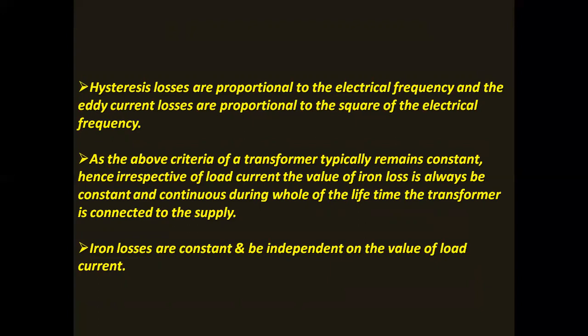As the above criteria of a transformer typically remain constant, irrespective of load current, the value of the iron loss is always constant and continuous during the whole lifetime the transformer is connected to the supply. Iron losses, therefore, are constant and independent of the value of the load current.